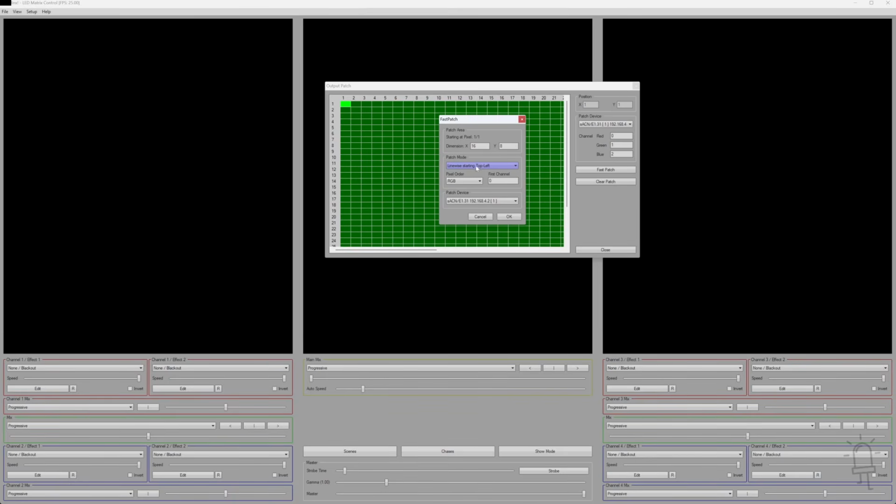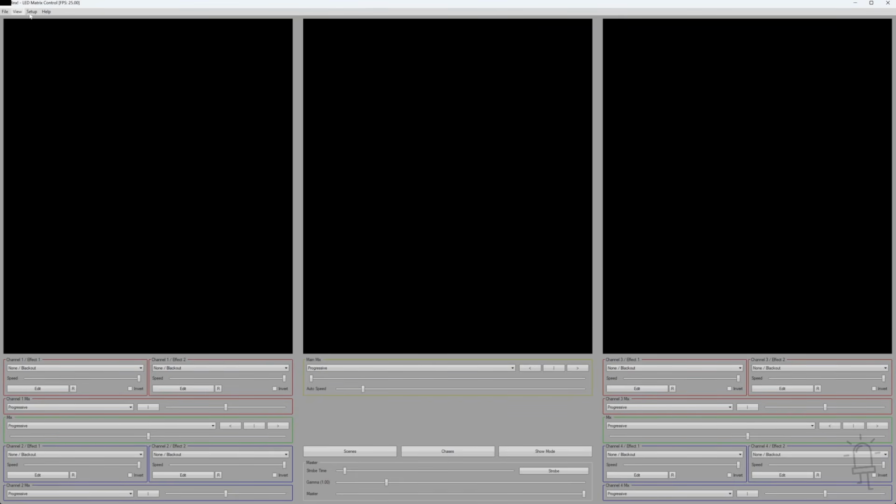One thing I will mention now is that my ESP32 also has the option to correct byte ordering, and you don't want to do it in both places. My strips aren't actually using RGB pixel order, they're using BGR. But at this point here, I don't want to convert them twice, so I'm just keeping them as RGB. So that is my matrix and my output setup.